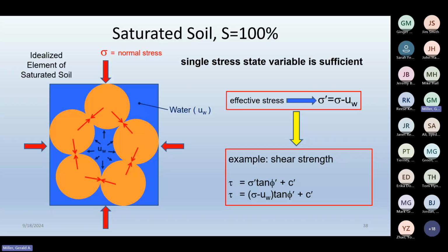You have a higher effective stress state, you have a stiffer soil because it's harder to move particles that have high contact stresses between them. Again, particles have to move for soil to experience volume change. And so you're going to have to overcome the stresses at those contacts to get soil to move.